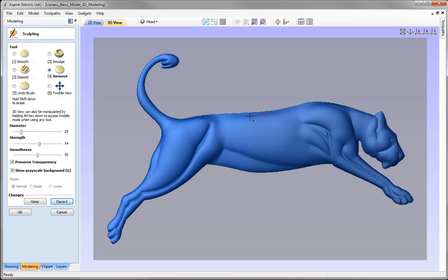So now what I'd like to do is look at blending the leg areas into the body, so this leg and this shoulder area. To do that we're going to use the Smudge tool again, except this time we're going to use a much larger brush, somewhere around 200, so a very big brush here. And then the strength, we're just going to really reduce that, somewhere around 25, 27 will do. Then all I'm doing is dragging material back and forth like so, and you can see we're just blending that leg in with the actual body there.